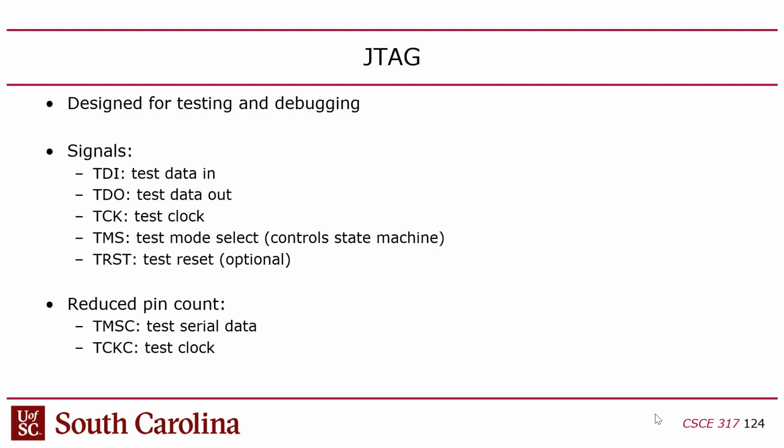Now you might say, well, why not just go straight JTAG? Because modern PCs don't have a JTAG output on them. That's why. If they did, there would be a 4-wire ribbon connector coming off of the PC on the board. But basically, every I/O device these days uses USB. So it does JTAG on top of USB.